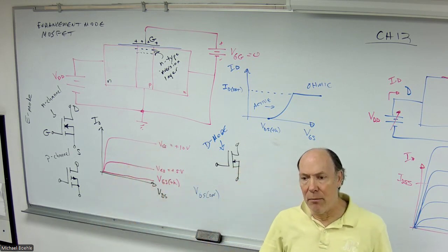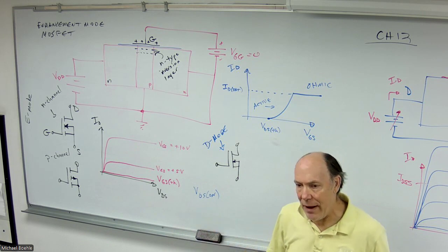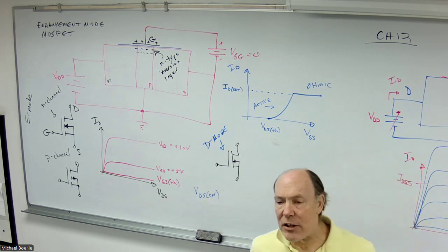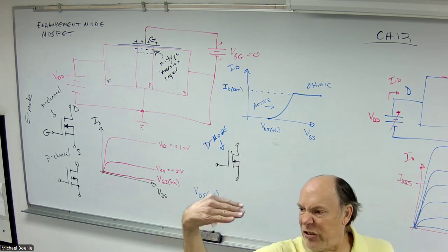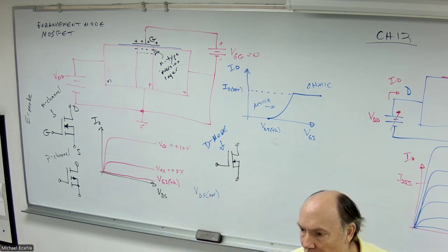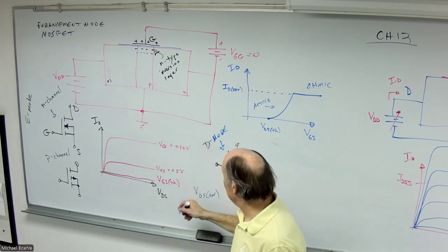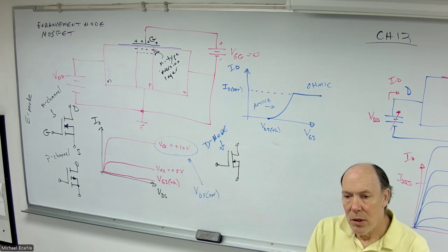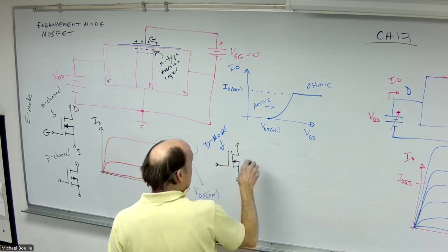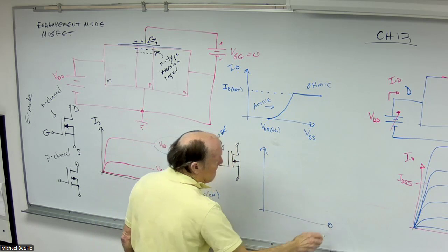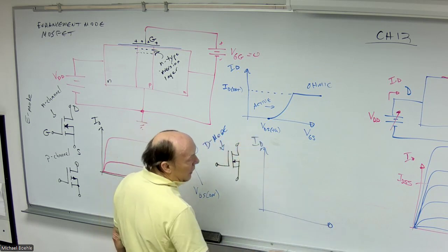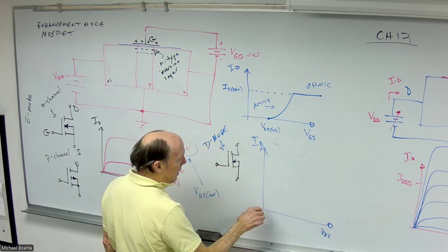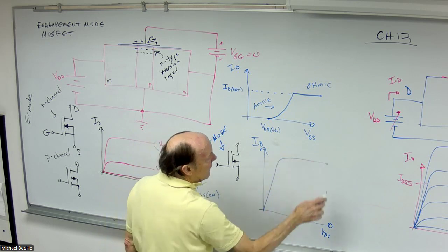You'll actually find that number for your experiment 35. The gate source on voltage is something the manufacturer is going to say, hey, you want to make sure this thing turns on? Apply this voltage to it. And whatever that voltage is, let's say it's 10 volts, well, then that's the curve that I'm going to look at. And I can just say, well, there's your drain current. Here is your drain source voltage. And for whatever that number is, there's my curve.